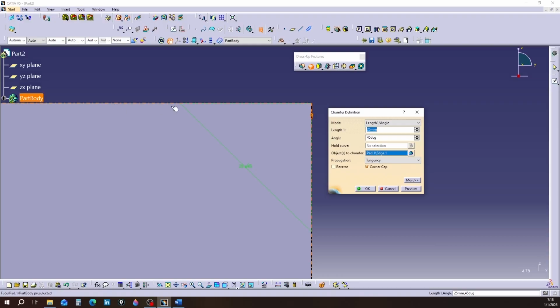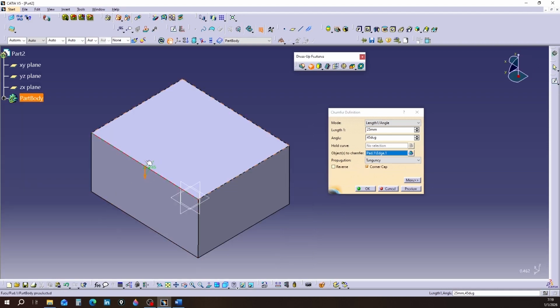Wherever this line intersects the horizontal surface of the part, a line is drawn from there to the starting point of the vertical line. In this way, a triangle is created. You will see the shape of the triangle in green. Now this triangle is subtracted from the edge of the cuboid. We can select multiple edges together.